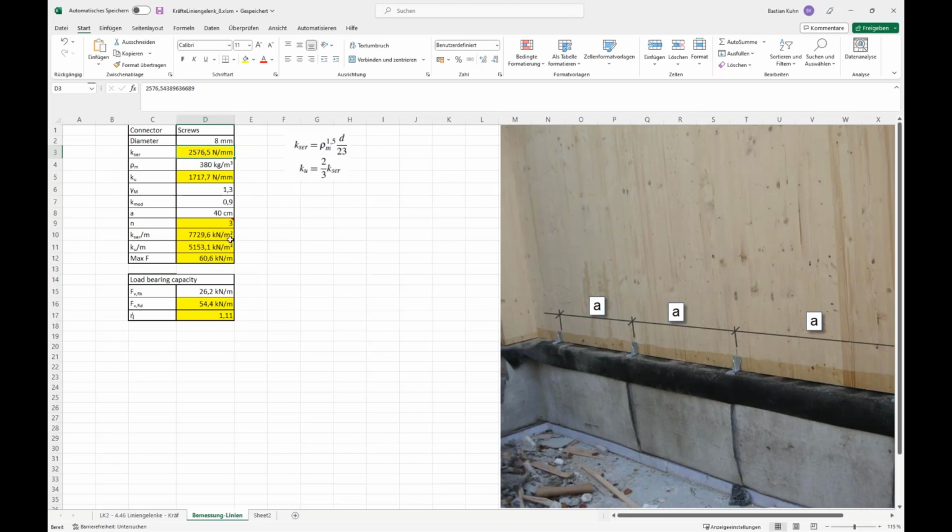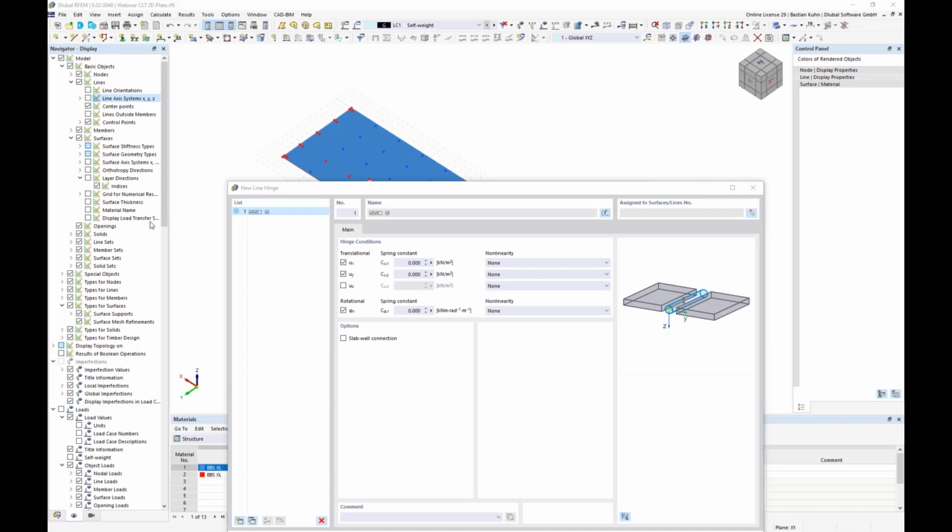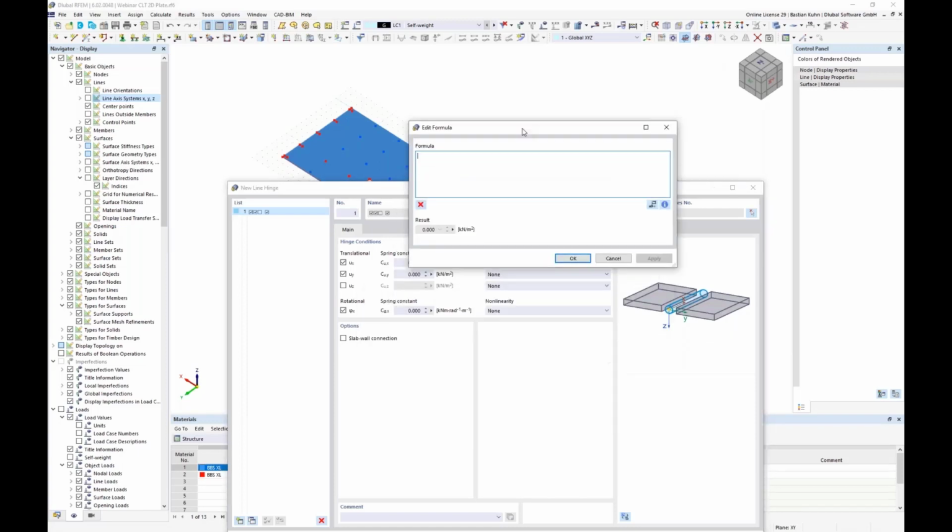And what's always important in your design process is how many connections per meter you can assign in there. So if you say now in this example 3, it will give you a stiffness of 7,729. If you use 4, 10,000 and so on. So the equation is very, very simple. You only use this added with this. Okay, sorry for this little excursion, but I wanted, as I said, not to just present it as heaven sent.